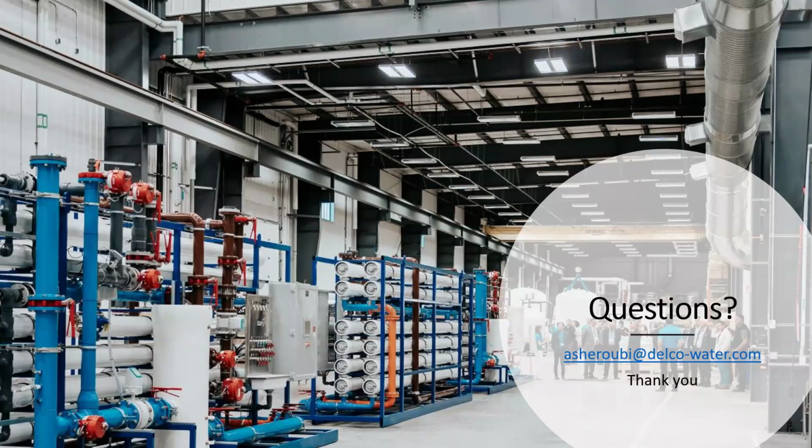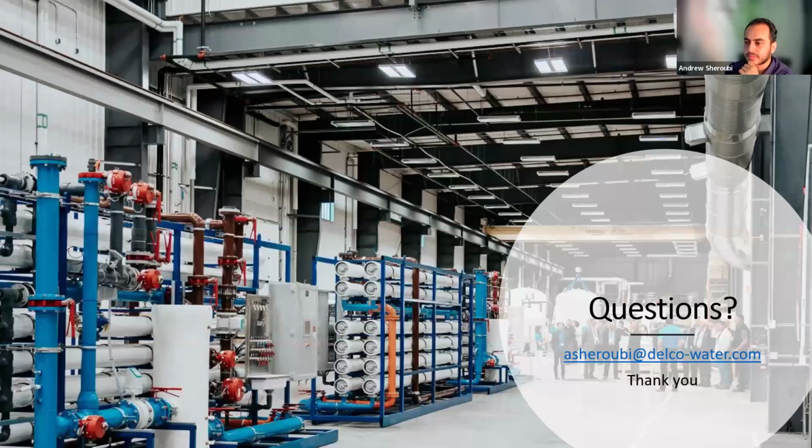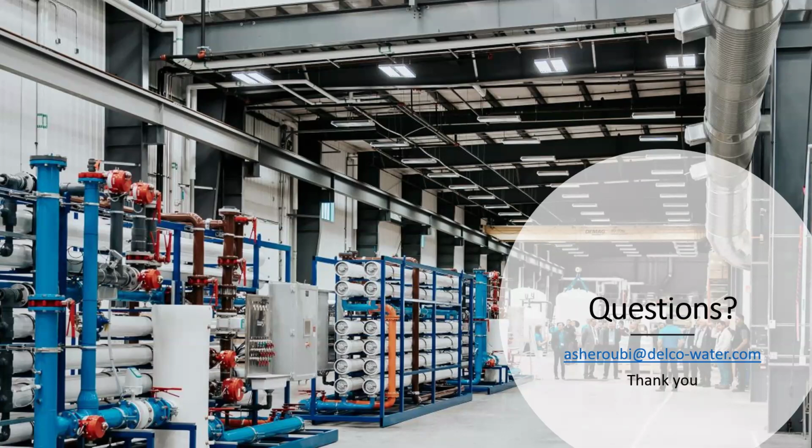The other thing, though, as well, is adding a little bit of alkalinity, because once the water goes through that reverse osmosis membrane, all alkalinity is virtually gone. Do you have any recommendations on those as well? Yes, there are a few different ways to add remineralization after an RO.